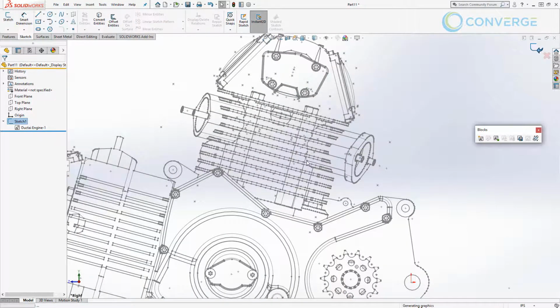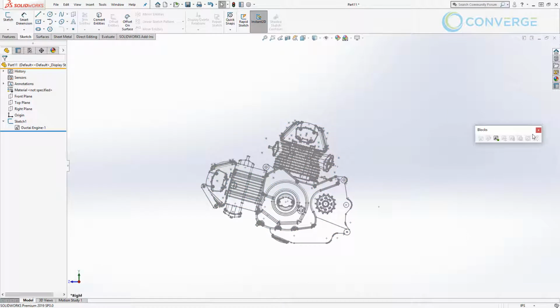Now what we've done is we've created this sketch in our file, our new part file, that contains a side view sketch block that gives us everything we need in terms of designing a part based on this, rather than having to deal with the assembly, maybe designing your parts in the context of an assembly. And this really keeps it a little bit cleaner at the part level. And of course, once we get to the assembly level, we can simply take this file, insert it into the assembly, and we'll know exactly where it is.